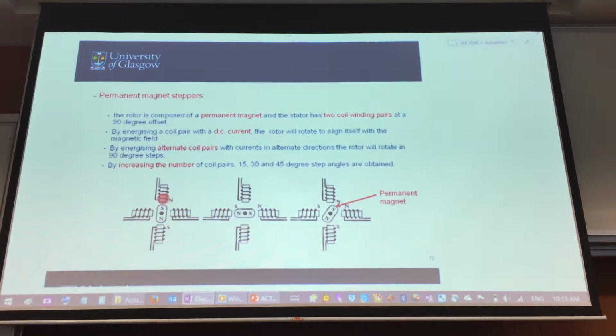Instead of having an electromagnet and a soft iron core, I changed this soft iron core into a magnet. Now that attraction force is going to be a lot larger. Why is this desirable? That's because if I have magnet and magnet, those two magnetic forces could move your core a lot more, giving it a much higher amount of torque.